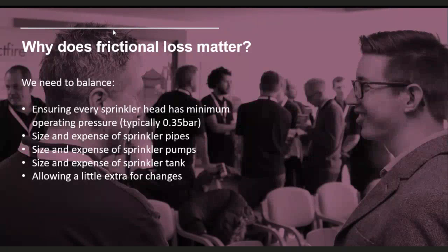Riser sizes, void spaces, everything is being squeezed and squeezed and squeezed. So yeah, we don't want to oversize our sprinkler pipes. We need to just work out what is the minimum size that is going to work with the calculations that we've got.